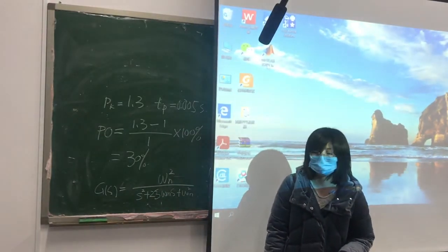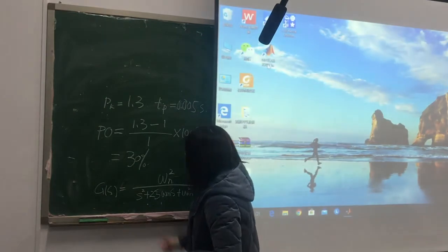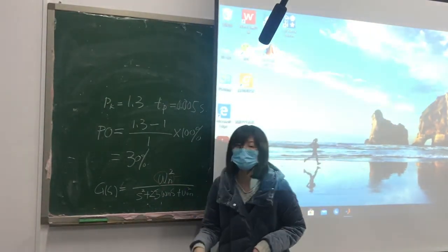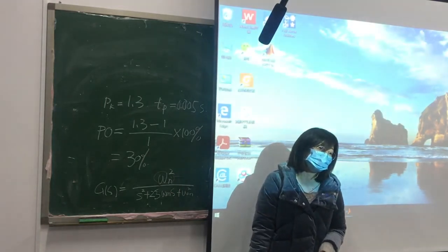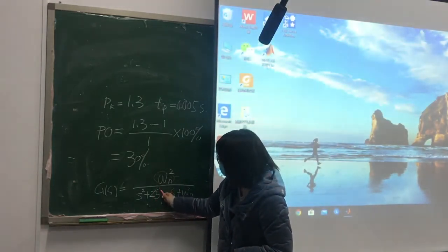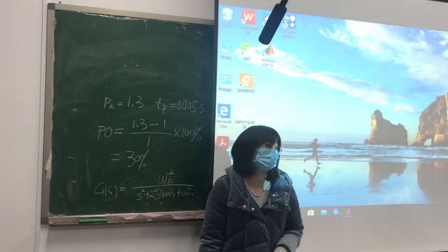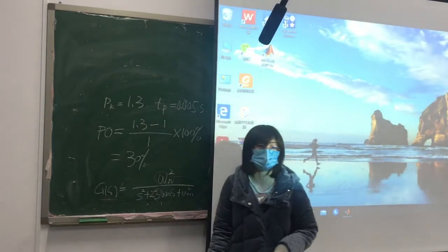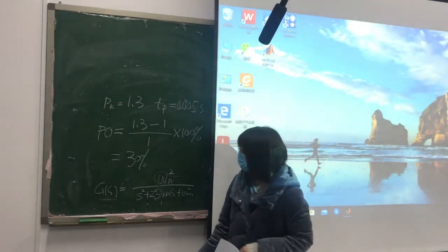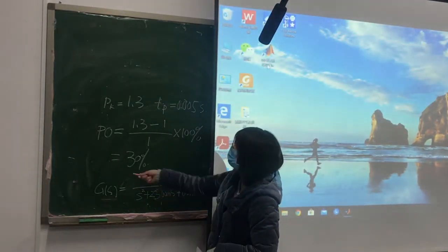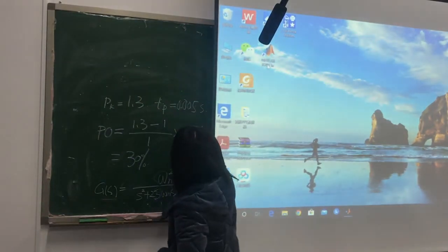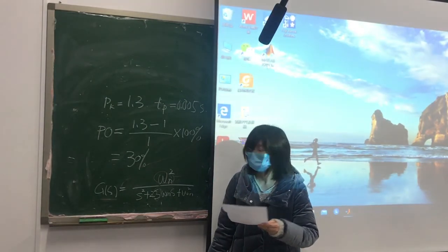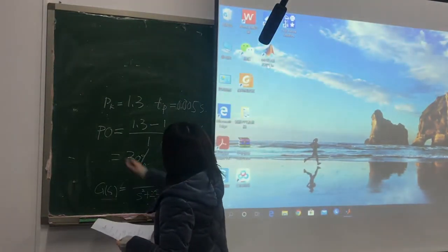Okay? So, first we should know omega n, the undamped natural frequency for second order system, and the zeta, the damping ratio, right? Yeah. If we know these two, then we can write the closed loop transfer function for the second order system. Then how to get omega n and zeta from the parameters we already know? Tp equals pi over omega n...